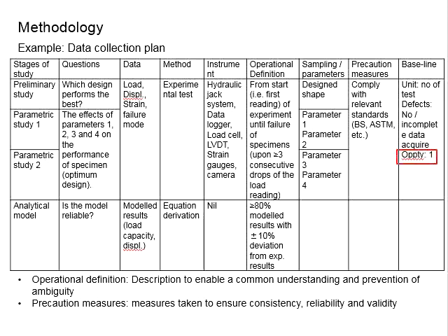And the opportunity here represents the number of specimens. Let's say now you are testing for the full-scale beam. It is rather troublesome to produce the big-scale beam, and it incurs costs for the specimens. It is not economical for you to have 3 specimens for one identical design. Therefore, you will have one opportunity. Knowing that you only have one opportunity, then you have to control the quality and the workmanship from the start until the end of the study.